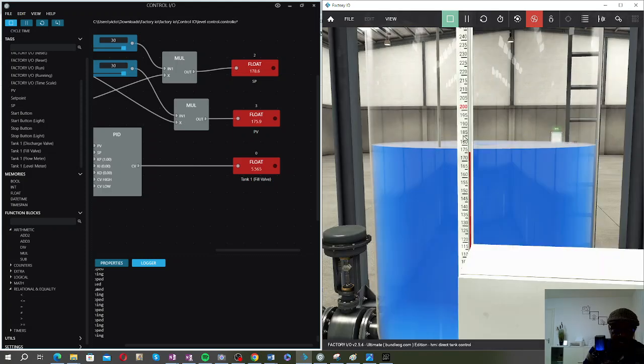That's around 180. But you can see that it's going up and down, up and down. So you want it to be as close as possible to the set point. But mind you that systems have their own inertia. Just like we have inertia in physics for moving bodies, there's also inertia in terms of heating and everything. And also it depends on the response.